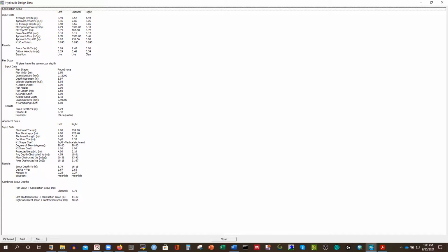So you have to check, you have to make sure by hand calculation and by using this model, because see, we are clicking only once and we are getting the value. So this may not be right. Most of the time we are using this equation, that equation, and in the model we don't have many options. But in reality, or if you use hand calculations, there are a lot of equations for calculating scour, so we can use those, and then you'll get the value from either hand calculation or from the model. So you have to use the maximum value, because these are the rules, right?